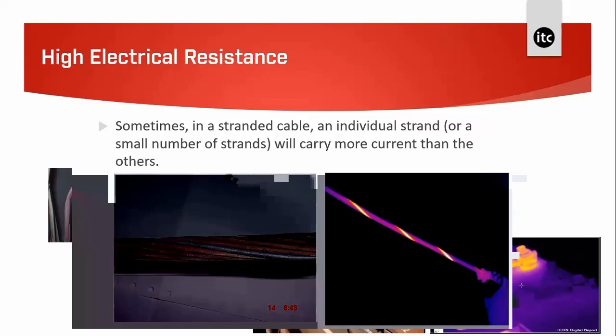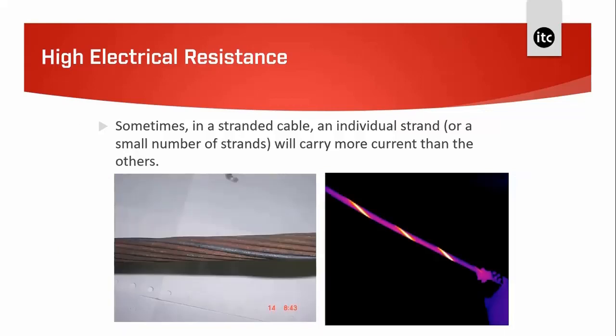or after a high resistance fault has been detected, it can be the case that the bad connection has been cleaned. If the person carrying out the repair does not clean between individual strands, there will be contact resistance between the strands, and usually one or more of the outer strands will carry all the current. It is important to recognize that the problem can be at either end, or in fact you have separate problems at both ends that contribute to the overall anomaly in the thermal image.